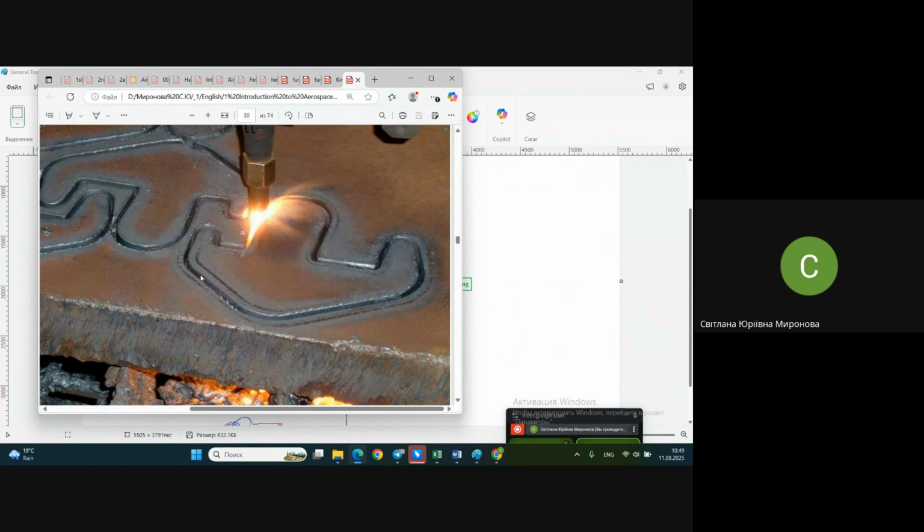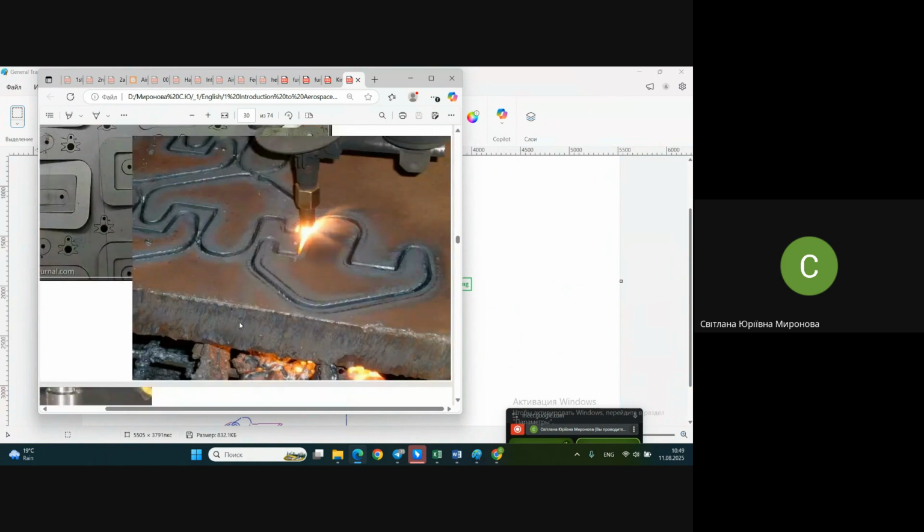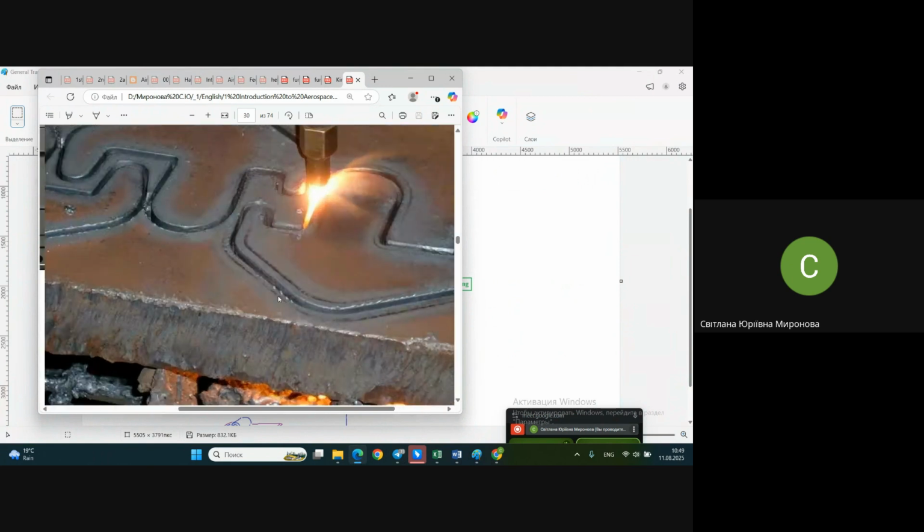In case you use milling for such a thickness, the mill should be in diameter at least equal to the thickness of the material. So do you imagine how much material you will waste while milling, in contrast to this plasma arc cutting? But plasma arc cutting, you see, results in overheating of material. What we see here, like additional flash, scratches or whatsoever, it doesn't matter. It's maybe removed next by abrasive machining, or by any manual mechanical machining, like filing, for instance.